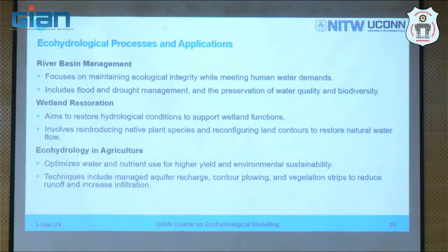And the idea of that buffer strip is that as runoff leaves the agricultural field and is getting into the stream, it interacts through that buffer area, it slows down the runoff, and because it slows down the runoff, it increases infiltration.